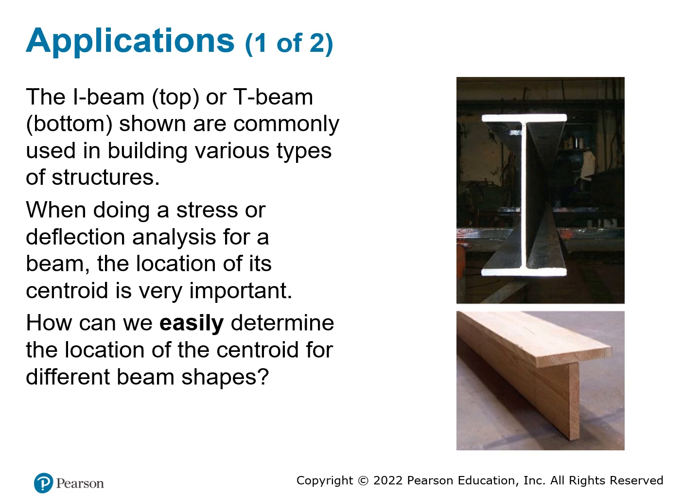We usually use so-called structural beams. I-beam and T-beam are very common. The reason that we use them is that in a certain orientation, the strength of these beams is strong. Instead of using a solid material, which will waste a lot of cost, this would do a similar function with less mass that you need.